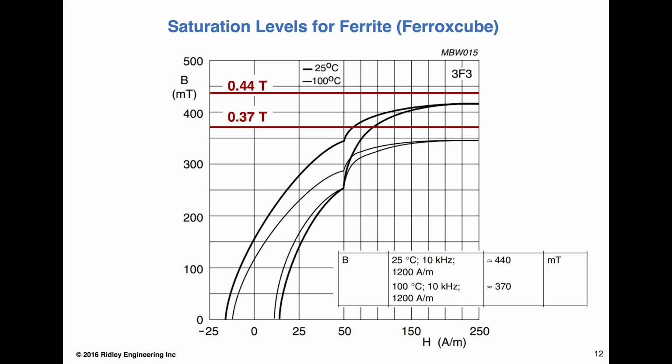I'd say we are seeing incremental improvements. I mean, we do see a new ferrite now and then, and it might get 20%, 30% better in terms of loss. Sometimes I did notice during the 90s, ferrites would come out called new ferrites, but they really weren't. They were old ferrites renamed, and they had suddenly found a good application. But again, nothing that I've seen is heading towards any great breakthrough.